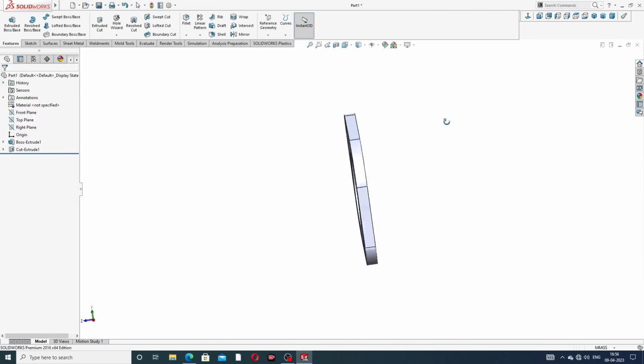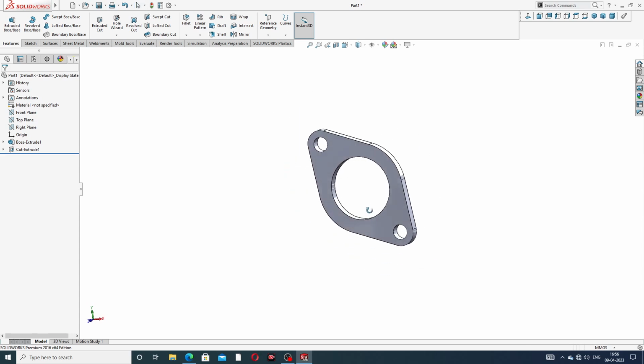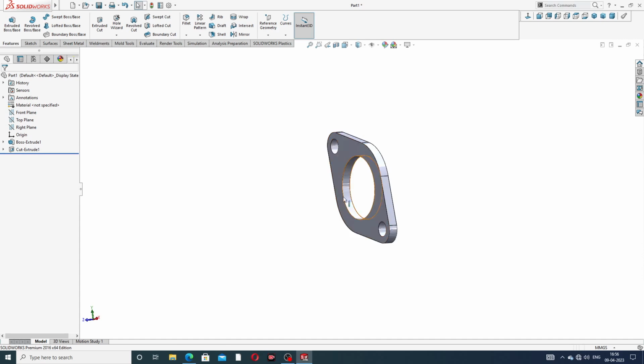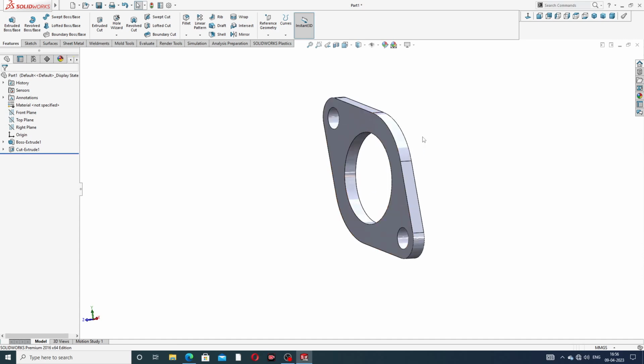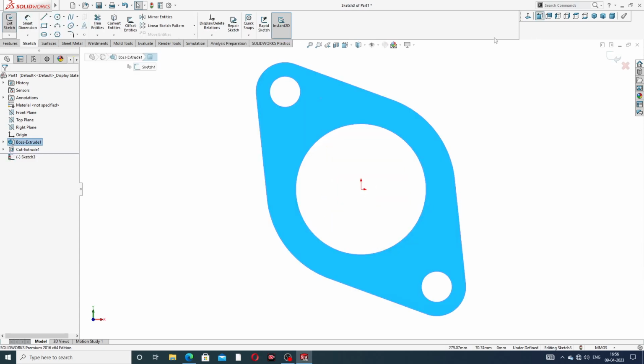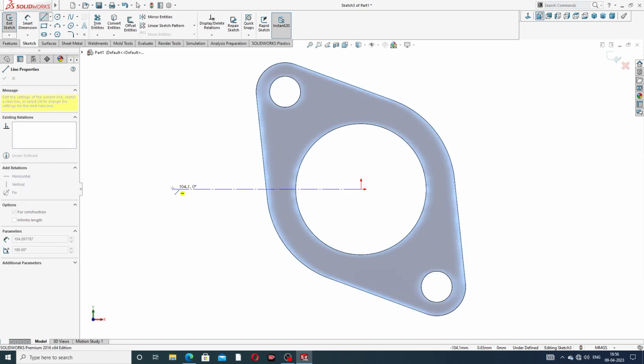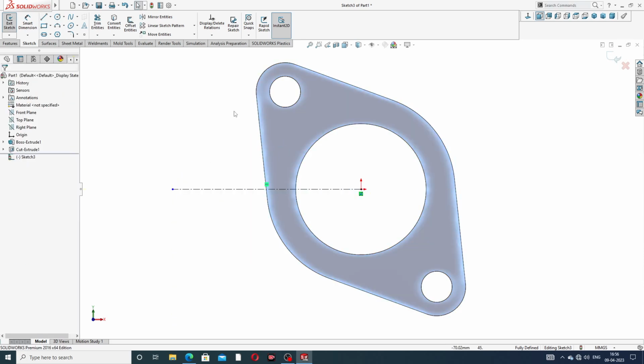Okay, this is perfect. This is one body in a clear design, but now use a pattern, and the pattern is 4, so there are 4 bodies. Select this face, sketch normal, and use a reference line. The reference line is very, very important because it is used for the pattern, and this line is horizontal. Okay, this is perfect.